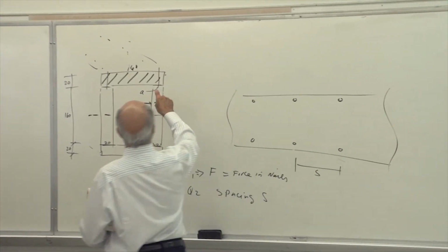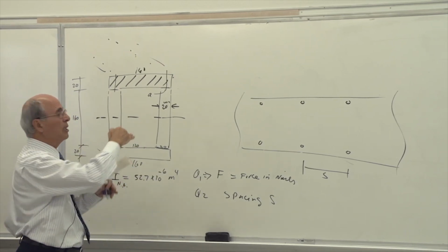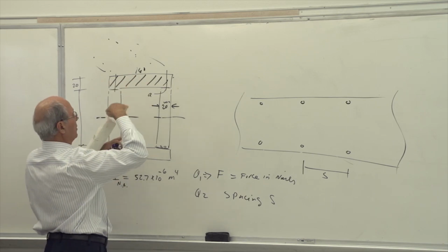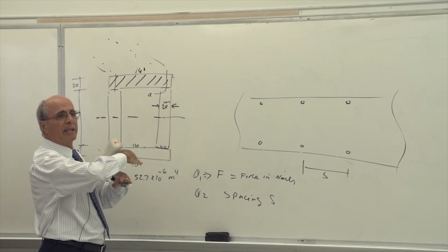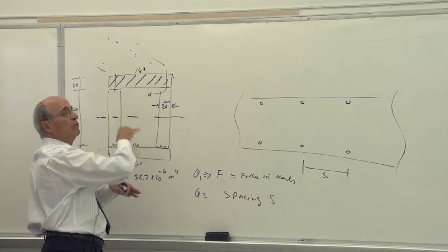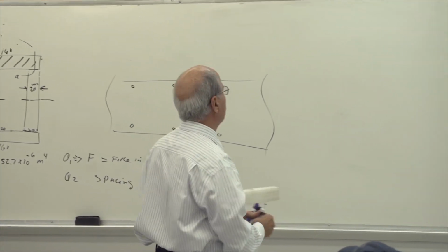Now, what happened to this nail? Are they under normal stress or under shear stresses? Look at it. This one wants to move this way, yes or no? And therefore, because of the horizontal movement, correct? Because of tau yx, is that correct? Therefore, these two nails will be in shear, which replaces the glue. Is that correct or not? That's the question we want to answer.